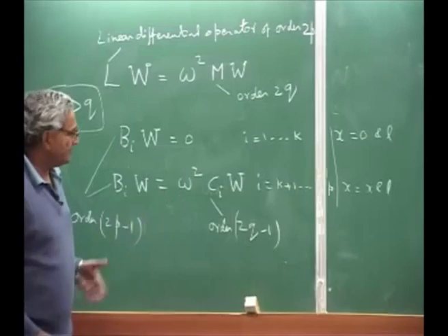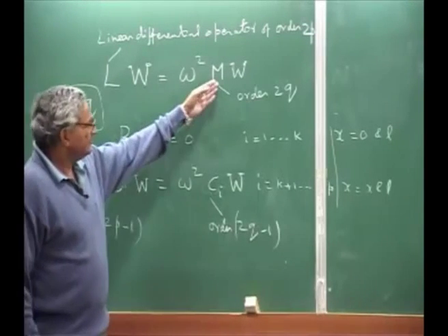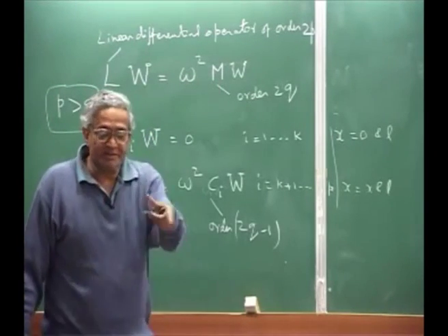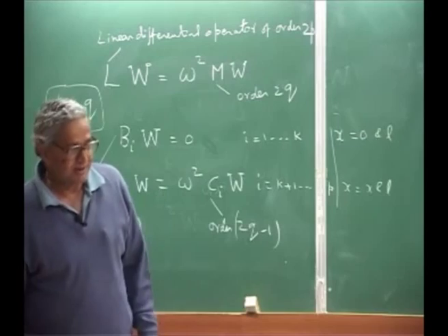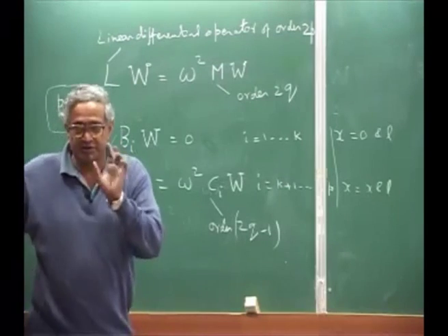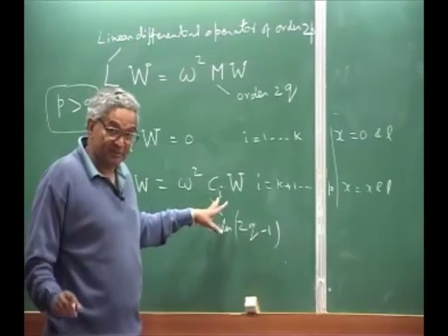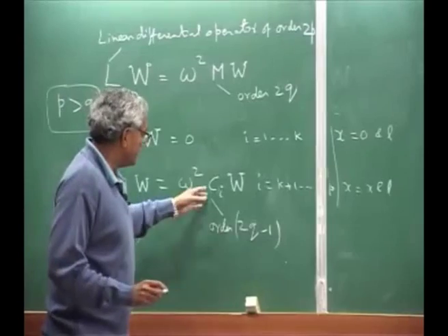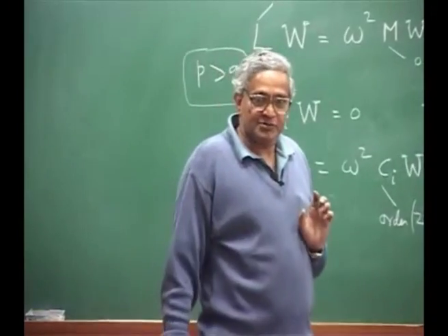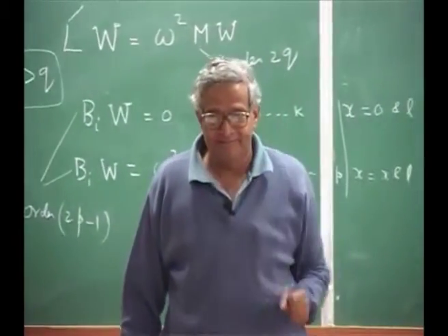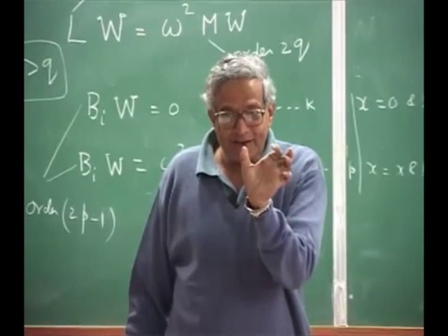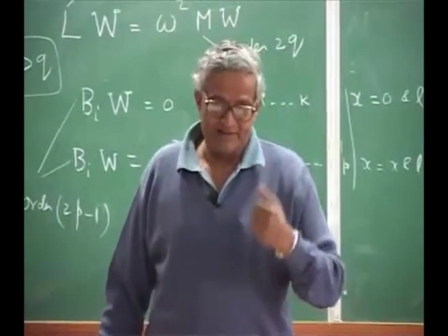But normally, if you have a tip mass, we didn't have any differential operator because there was no difference. But where will you get the differential operator? Suppose in this situation, tip mass, or we didn't allow any, that mass is distributed mass we took. Here also you may get some differential operator sometime. That's why I am saying tip mass goes here. The distributed mass, you put it as a mass. Suppose you add rotation, that is rotary inertia of the elemental mass, and take its kinetic energy.